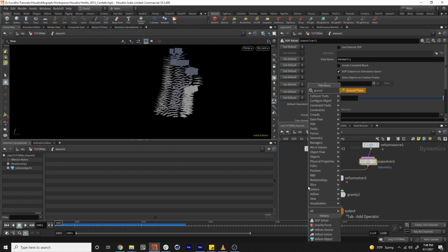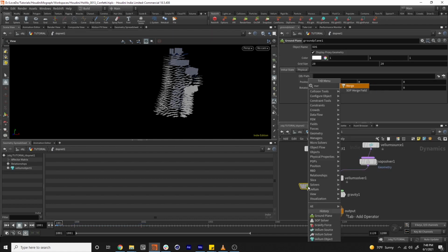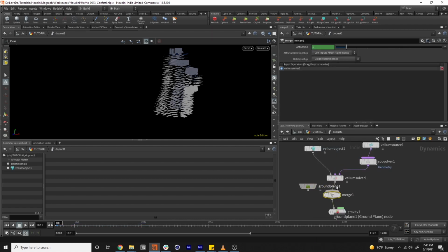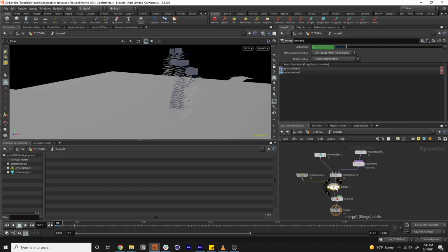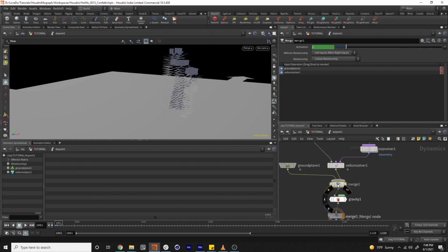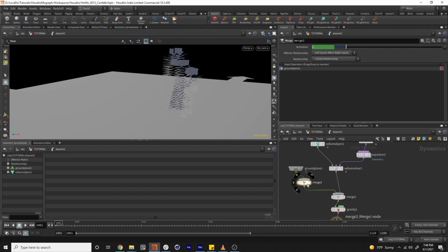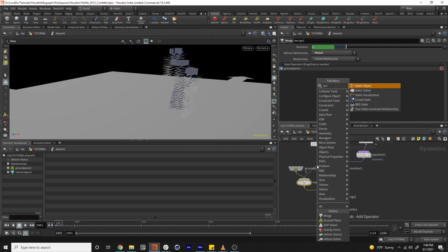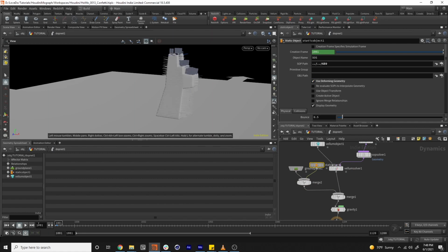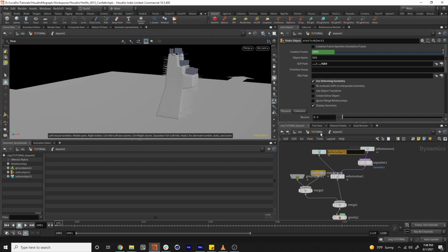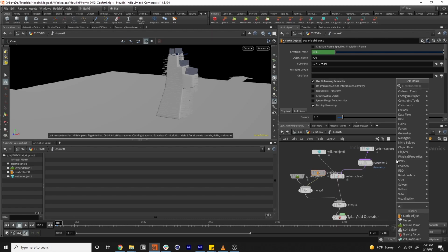These pieces seem to just kind of fly everywhere. So first let's make a ground plane and merge that in using Shift R to make sure that it comes in from the left. Now make another merge and set it to mutual. Then make a static object. Now grab our original geo and set this to deforming so that the object will collide with the base.